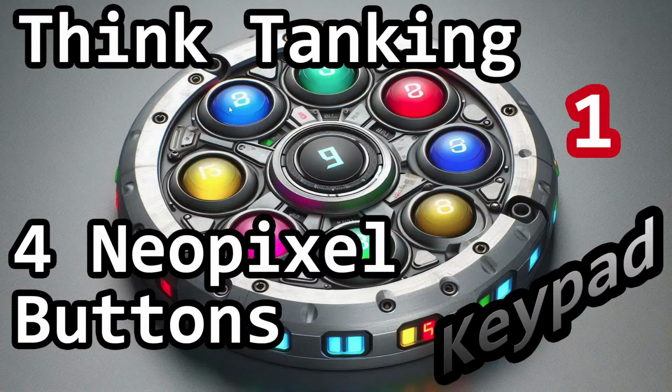They don't have to be round buttons, they can be segments, but whatever it is. Obviously the bigger the button, the more you've got to mill out, and the ability for it to stay stable in its receptacle part is diminished. So yeah, we've got all those considerations to look at.